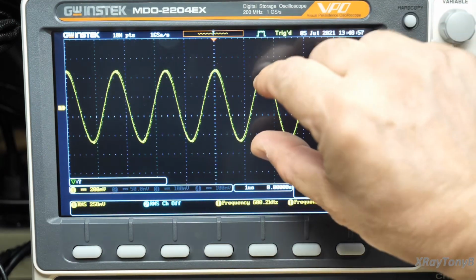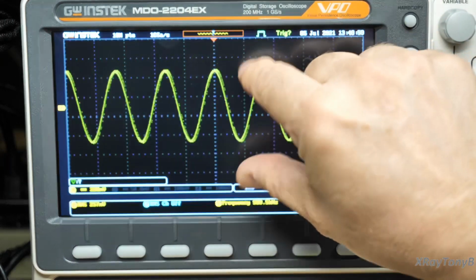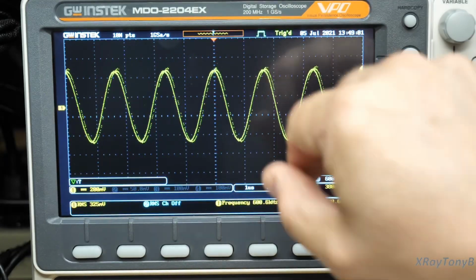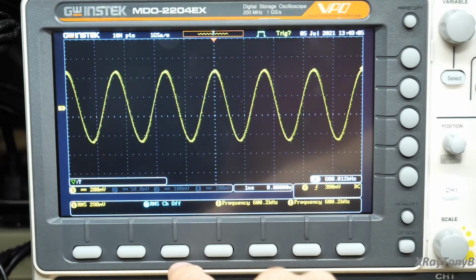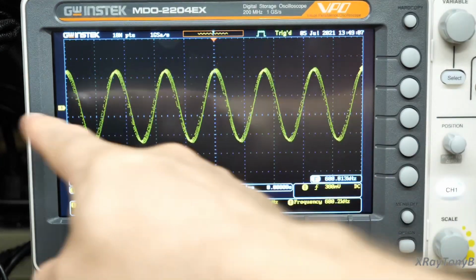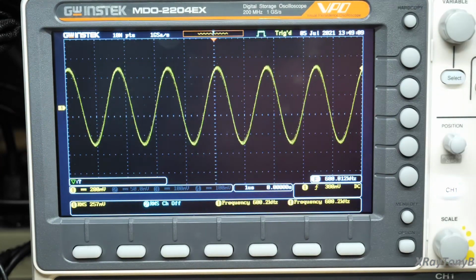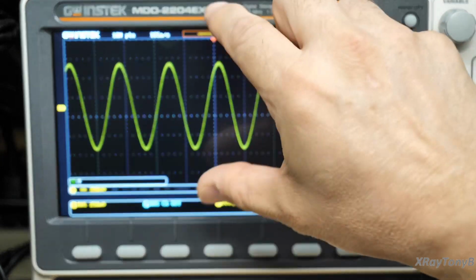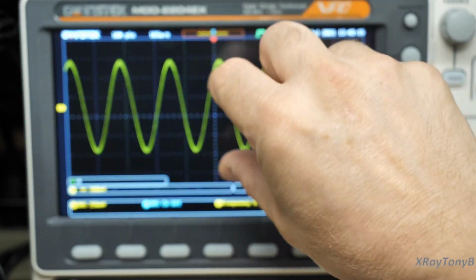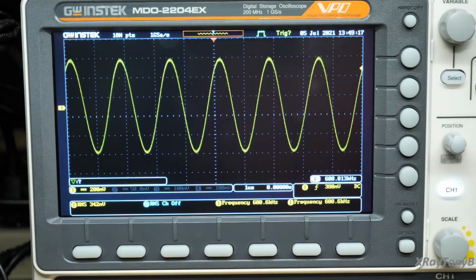It's actually making the amplitude of that signal go up and down. Okay? The frequency is never changing, if you notice. It's still a 600 kilohertz signal on top of it that's carrying it, but you're just changing the amplitude or the power or the volume of that signal.